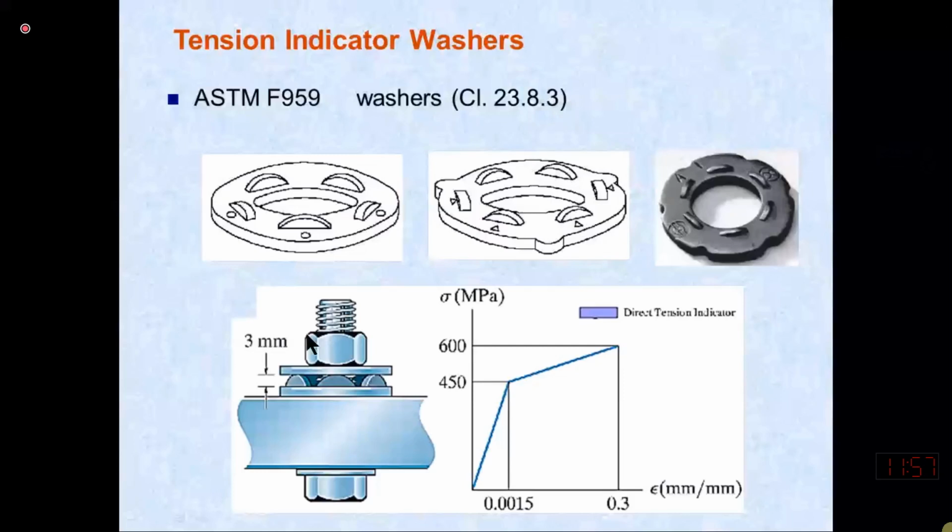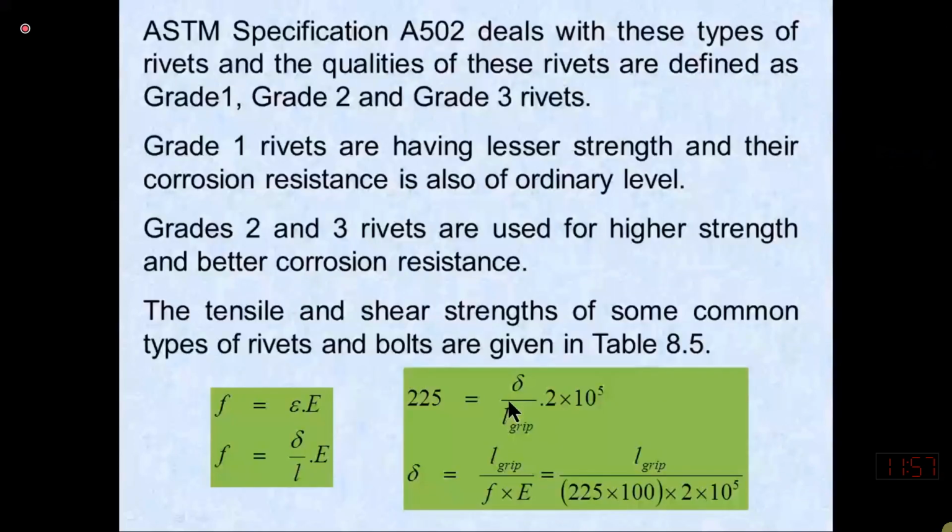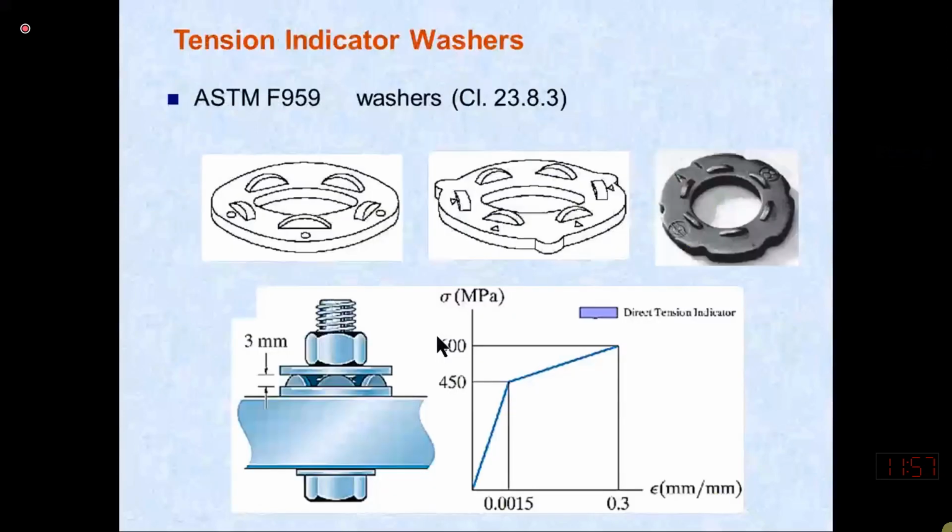And after stretching, if I tighten the bolt, the bolt material will tend to come back to its original position, which is providing the compressive force on the plate, or a high contact pressure, which is protecting the plate from slipping in the lateral direction. So this was the case. This is the type of forces if I am providing strains in the bolt, and this is how the pre-tensioning is increasing. You don't need to memorize this case, you just need to understand the basic philosophy.